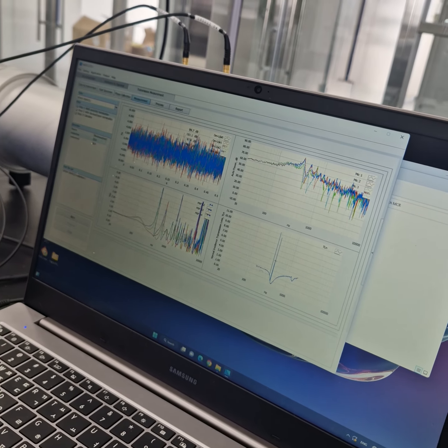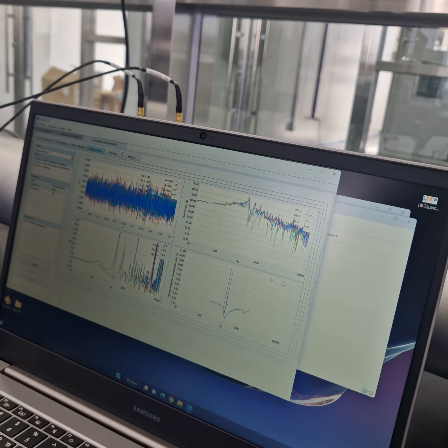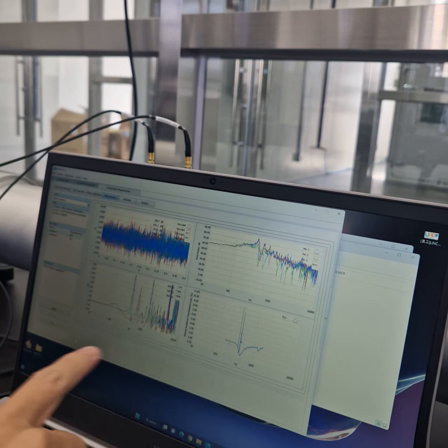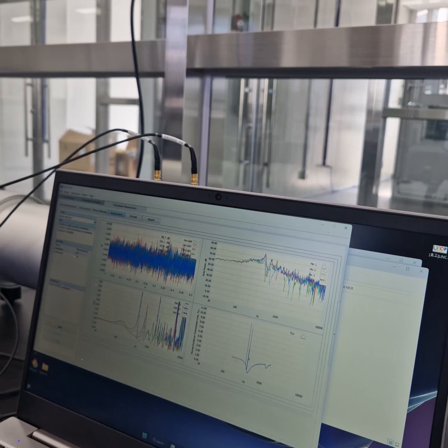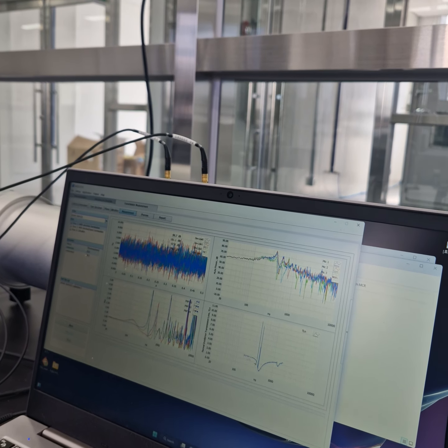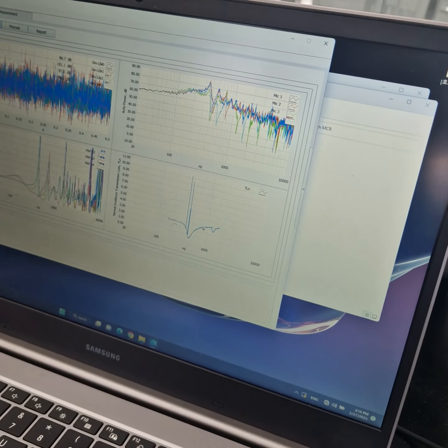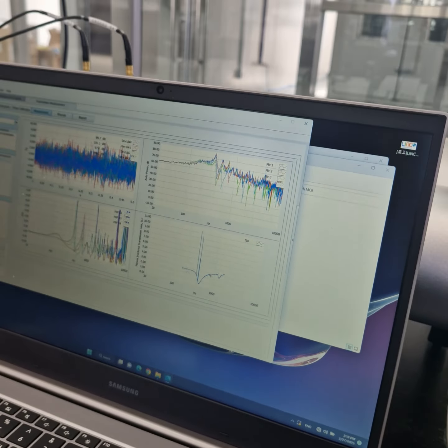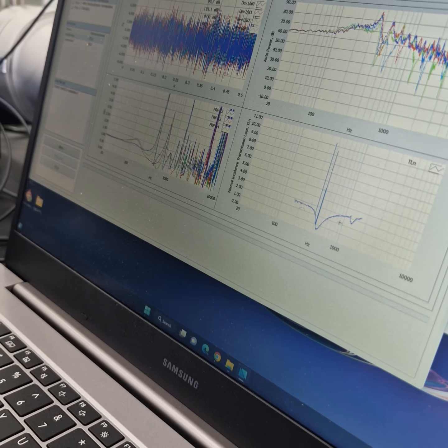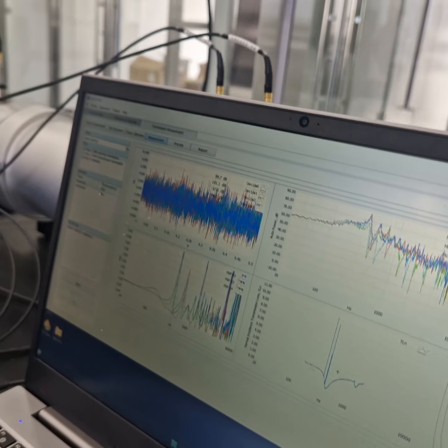And sometimes there are going to be some peaks. Peaks? Yes, so this is some variation. So maybe in the data processing, you can just take it out, because this is not the correct data. Sometimes you need to take it out manually. But this curve, the trend is something like this. You see, the transmission loss is around 3 decibel, which makes sense for this type of material.